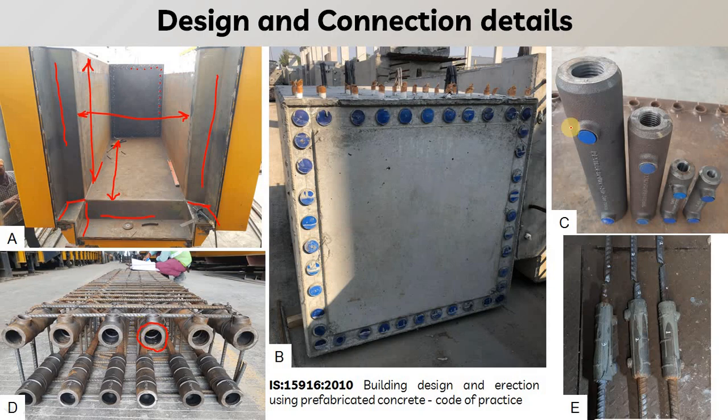So this is the connection which will be used for precast to precast connection. In the wall panel video we have seen how the dowel tube is used to connect the precast element vertically. In this video we will see connection type 2, material 2, which is known as the dextra grout. So this is known as the dextra coupler. This is the coupler that is used.